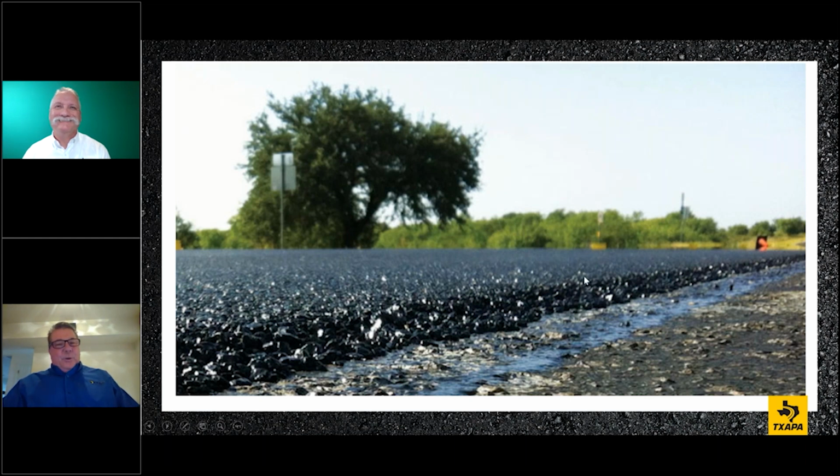But again, if you do have a tender mix, a mix that's not acting properly, or a poor-acting mix, the very first thing I go back to is that aggregate. I make sure my aggregate is consistent with what I designed with, and I work backwards. Then I'll work with the oil and see what's going on with that, and then I'll look at temperatures. So there are different processes to go through, and we'll talk about that as we go on through our fundamentals. But again, with the aggregate, look at the angularity, look at the cleanliness, and make sure we don't have that clay in there.